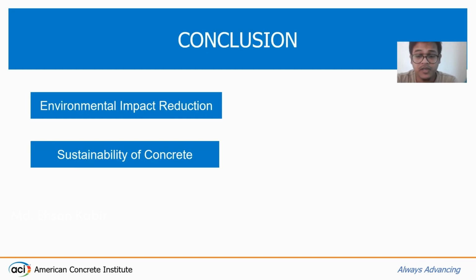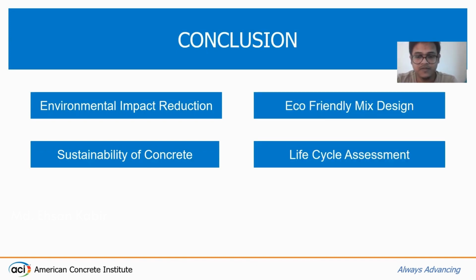Ecoconcrete eliminates the negative impacts of the cement industry, minimizing the environmental impacts. Therefore, we must always attempt to replace as much cement as possible with supplementary cementitious materials, especially those that are byproducts of industrial processes. Environmental aspects depend on mix design and material use.